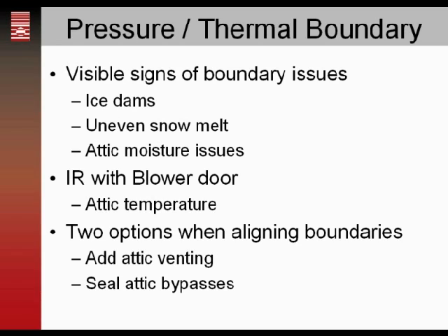Infrared with blower door also helps find if there's a lot of attic bypasses. In this example, we suspected a lot of attic bypasses because of the severity of the problem. So we did an infrared camera scan before the blower door test. We did the blower door test and then did the infrared camera scan with the blower door running, and we didn't find any bypasses, and that did not seem right.